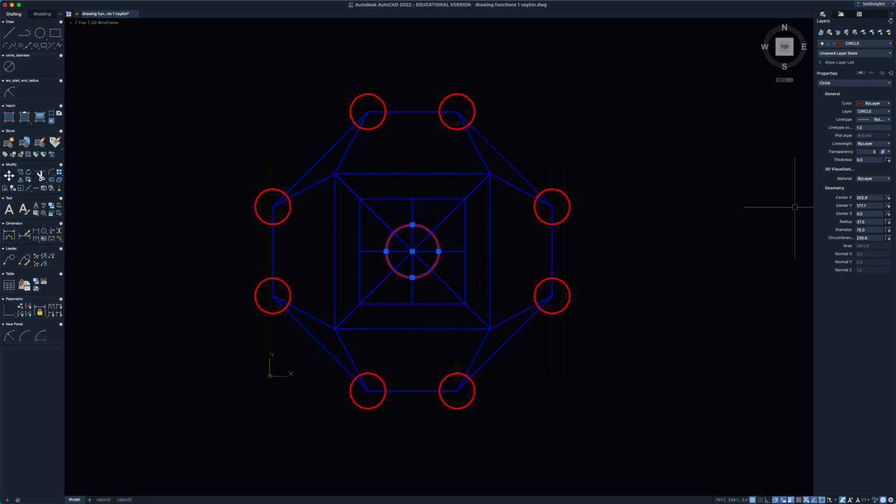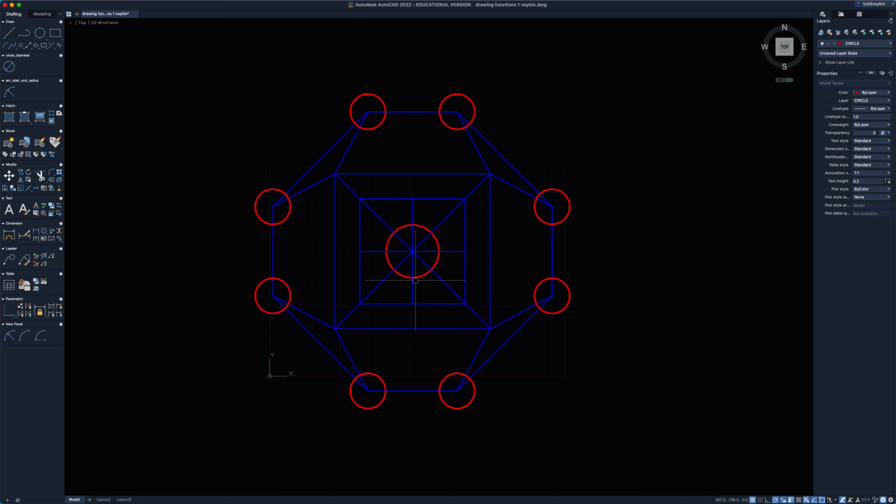Now if I look over to the right hand side in the properties inspector, you can see there it is, radius 37.5, diameter 75, and it gives us a bunch of other information as well. There's circumference, where is the X and Y point. So now we could change this by just clicking on it and going 50, or clicking on it and going 75. But we don't want that. We want to click on that and go 37.5. Done.